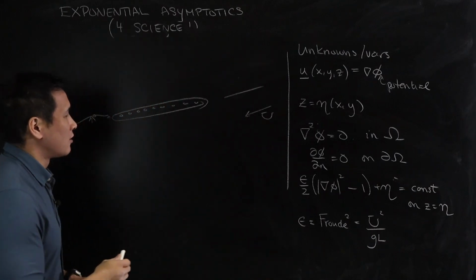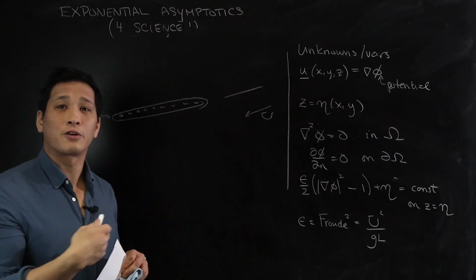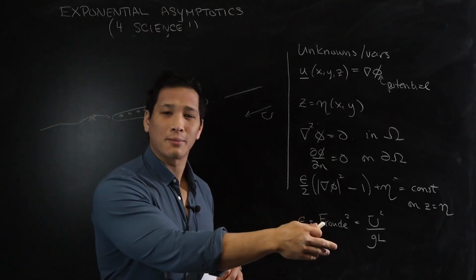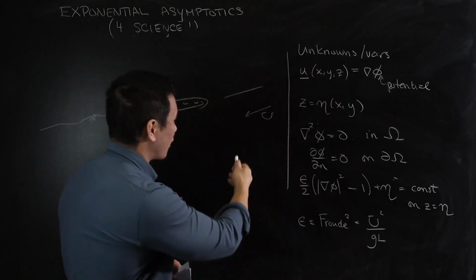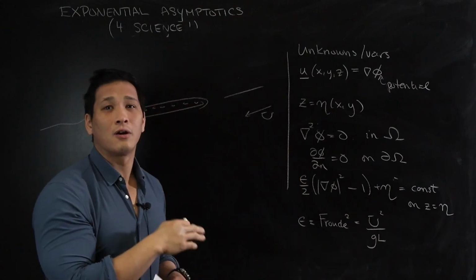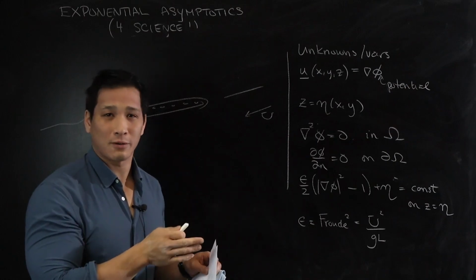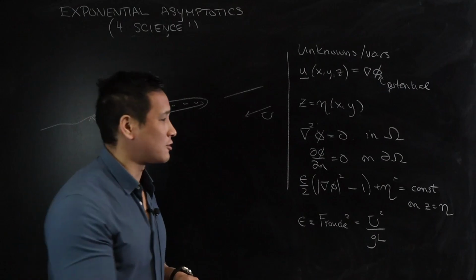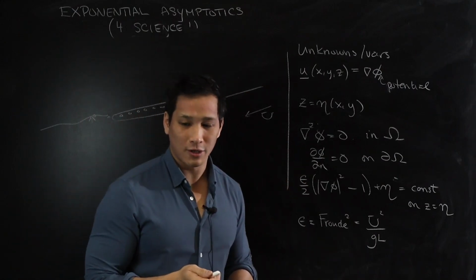In particular, if your ship is infinitely thin, you might think that to a first approximation, you can think of the water as just passing right through the ship, right? And so it turns out that actually, if the flow is coming in at speed u here, the first approximation might be that I don't even have the ship at all. I just have uniform flow right through. And so that allows you to hopefully try to simplify and linearize some of these equations. Okay?